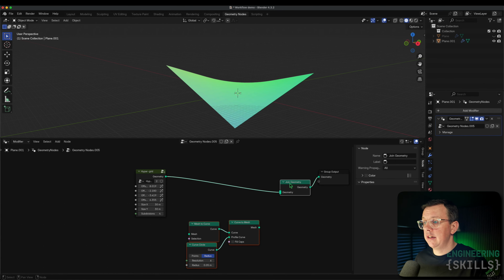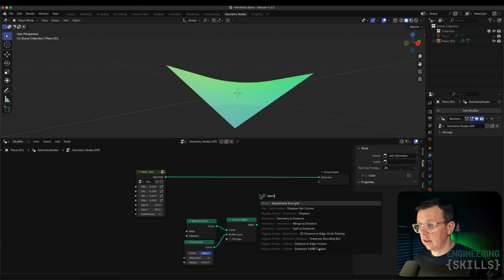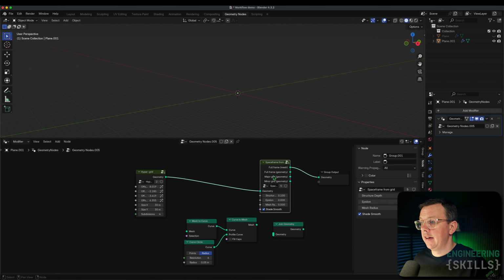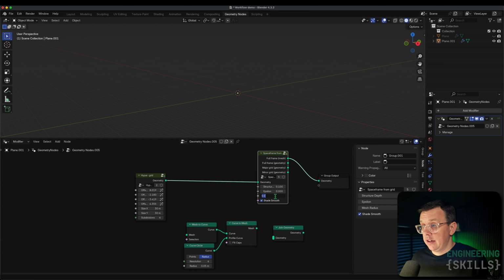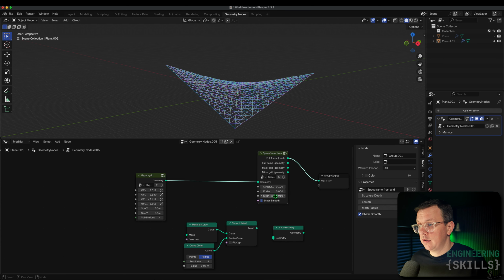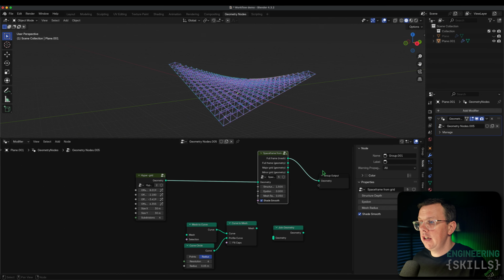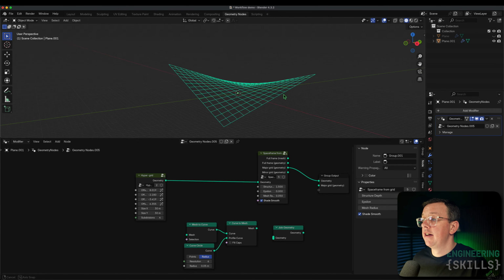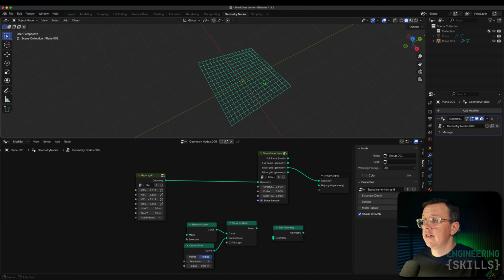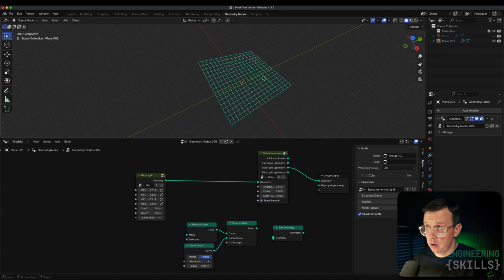All we actually need here is our space frame again, so we can drop that in there, and change the size of our elements again. Let's go with something like 0.05, change the structural depth to 1.5, and now you can see the influence of the tuning parameter. If I look at the bottom grid, in fact let's pipe it in here instead. So this is our grid, right? This is the grid that the whole space frame springs up from, and it's exactly the same as the grid that we just generated down here.